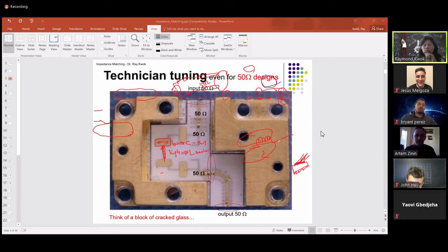So again, people will typically do this up to 1 gigahertz, 2 gigahertz max. If you want to build circuits for cable TV at 12 gigahertz, that is very difficult to control. At high frequency you need some kind of inductance, so you have a coil around a winding of coils. At higher frequency, because the impedance is j omega L, you want to lower your inductance. So at very high frequency, your number of turns usually gets smaller and smaller.